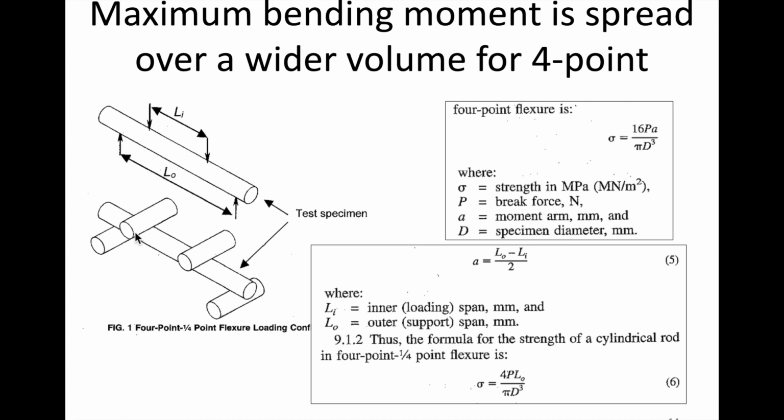And then these are the 4 contact points, because we are going to be using 4-point bend. You see the 2 under the inner span, which is the top, and then the outer span is further apart on the bottom. By moving those closer and closer together, we apply a force, and that is a bending force, because it basically causes the sample to bend downward, to deflect down.